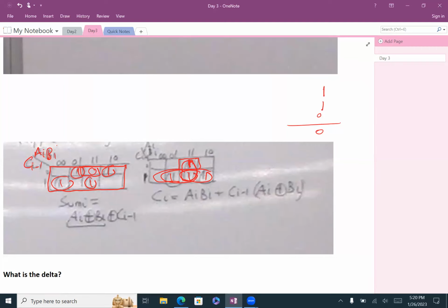Where is the logic, where is the condition we can decide we have a carry or not, long before we even get to the current stage? So how can we do that? We have something called the generation concept. So when will you have a carry out, when the carry here equals 1, if your input carry in this stage equals 0, what is the condition for that?